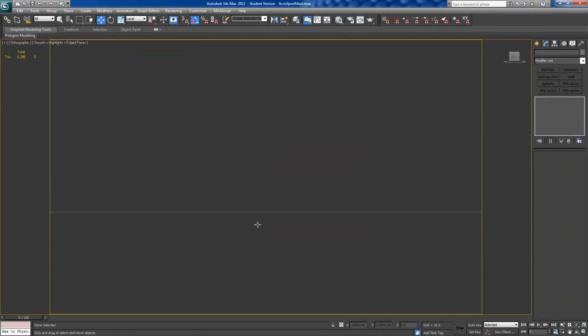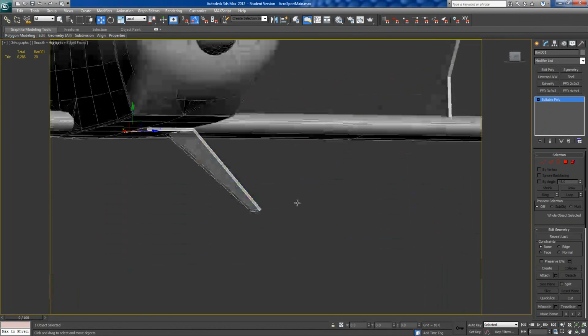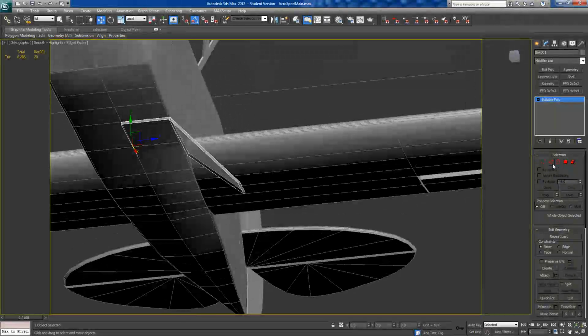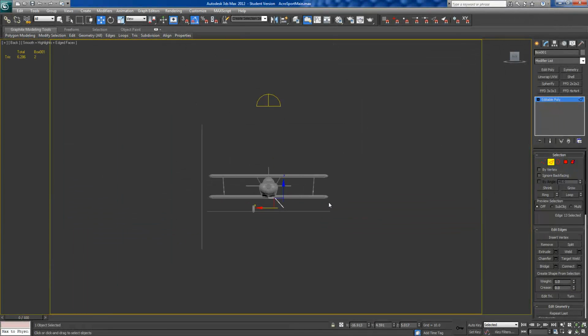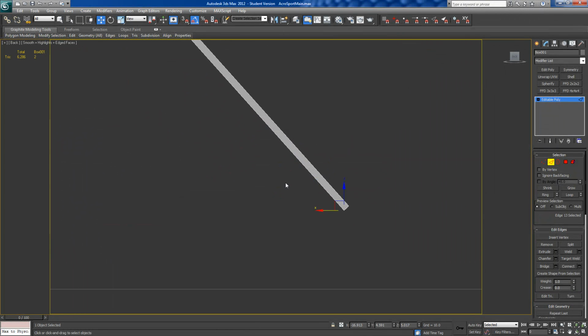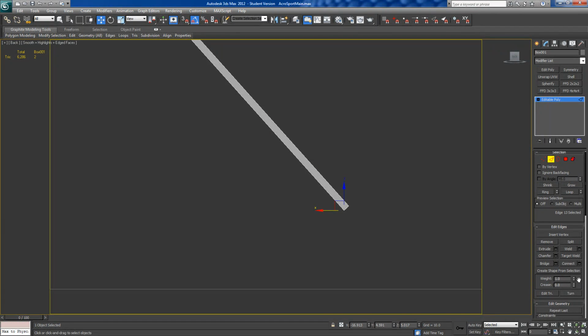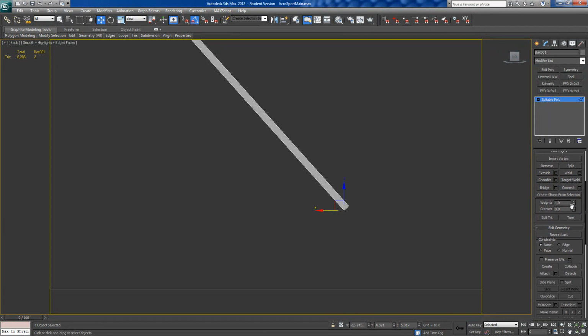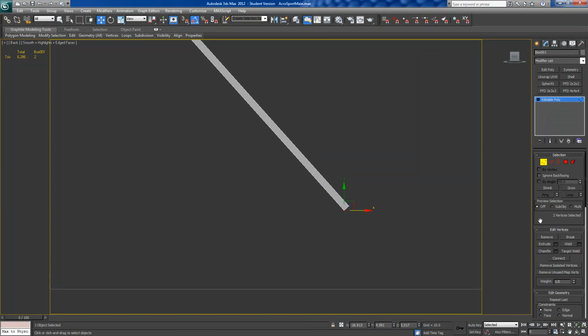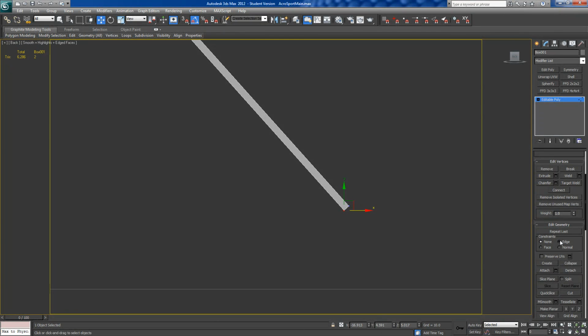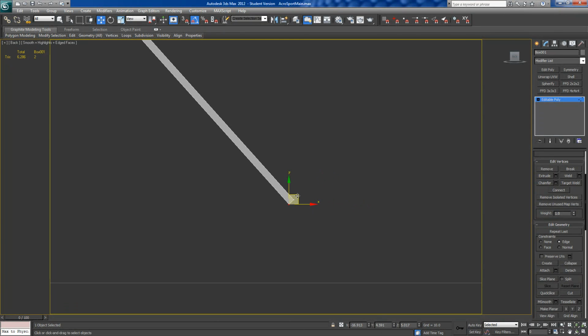Okay, so you hide this wheel, and we're going to do the same thing. So I'm going to grab that edge and convert that to vertex by holding Control. Go to edge and just going to pull up on these, oops, until this is nice and flat.